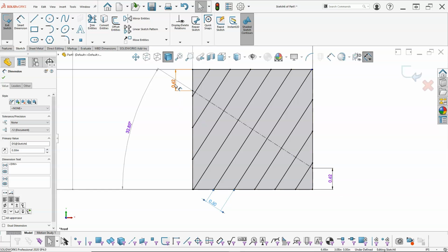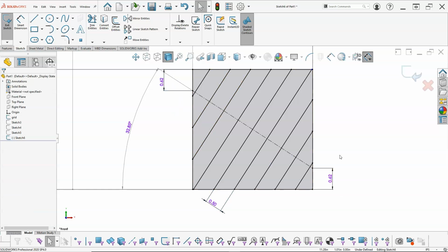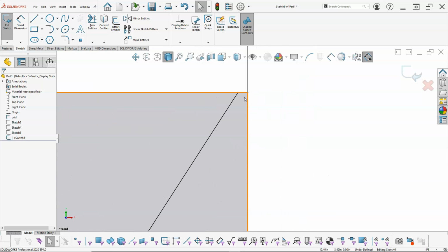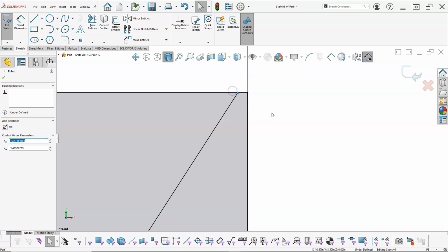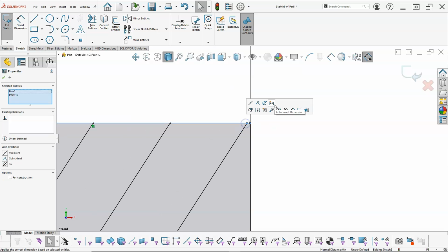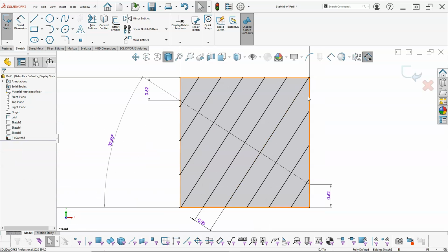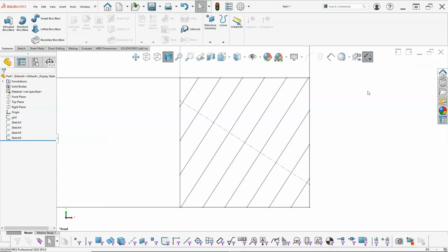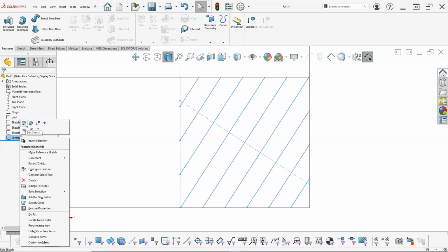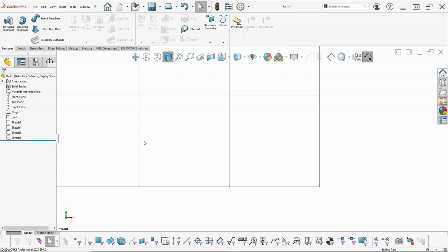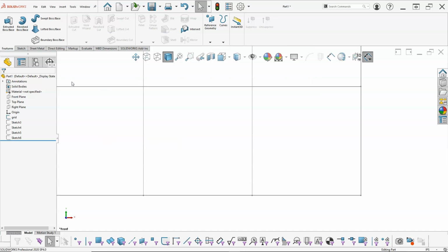Interestingly enough, I don't see any blue dots. Oh yeah, I do. There we go. So it's going to be one of those that hides in there. So let's make sure that goes coincident. And it didn't force it to over-define, but those are going to be the little things that you'll need to be able to key in on and force this to go fully defined. And if we don't locate it, it will usually appear eventually in the process of creating the features.